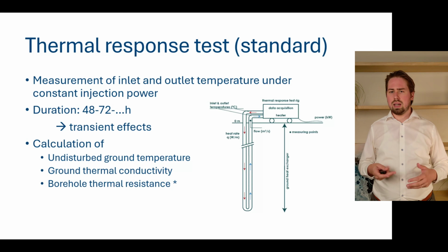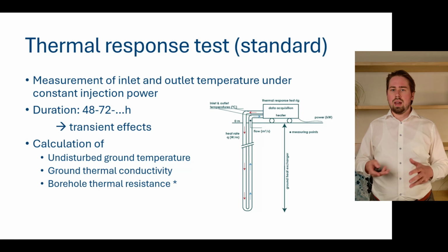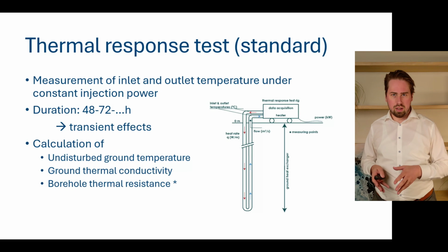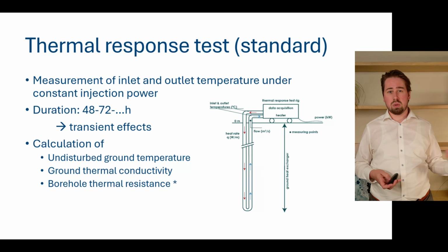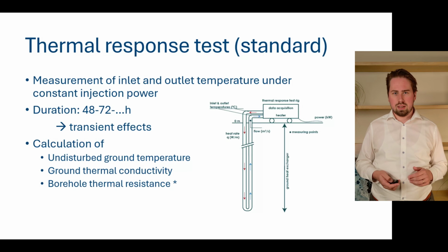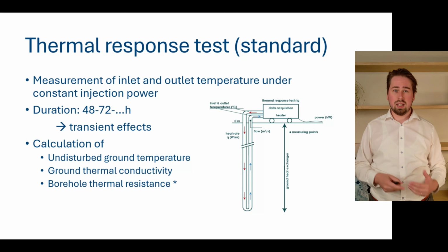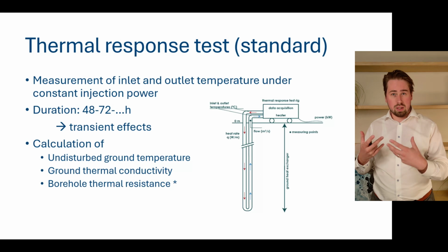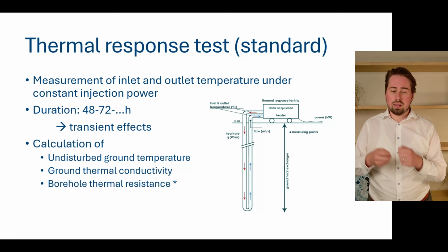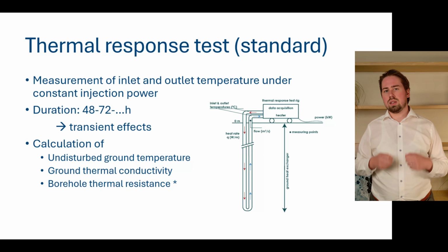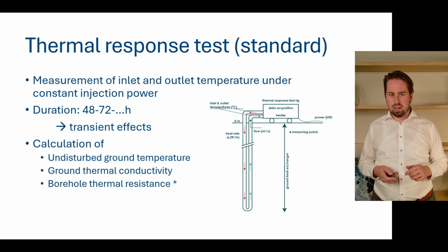We discussed already many times that the borehole resistance depends on your type of antifreeze, your flow rate, your temperature, and so forth. And typically these TRT tests are done with pure water. So if your case has an antifreeze added to it, your viscosity will be different and hence will your turbulence and also your borehole resistance. So please be careful when using the measured borehole resistance for your design and make sure that the conditions by which the borehole resistance was measured are actually representative for your actual design. If it's not, please just calculate the borehole resistance in GHEtool directly.